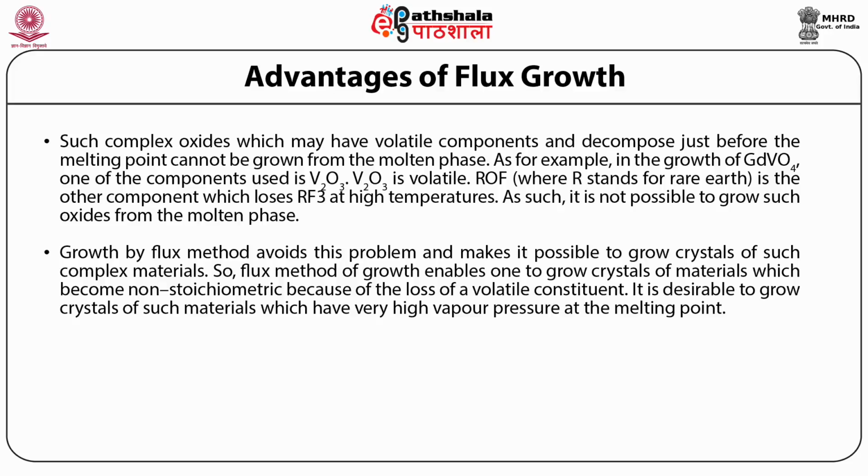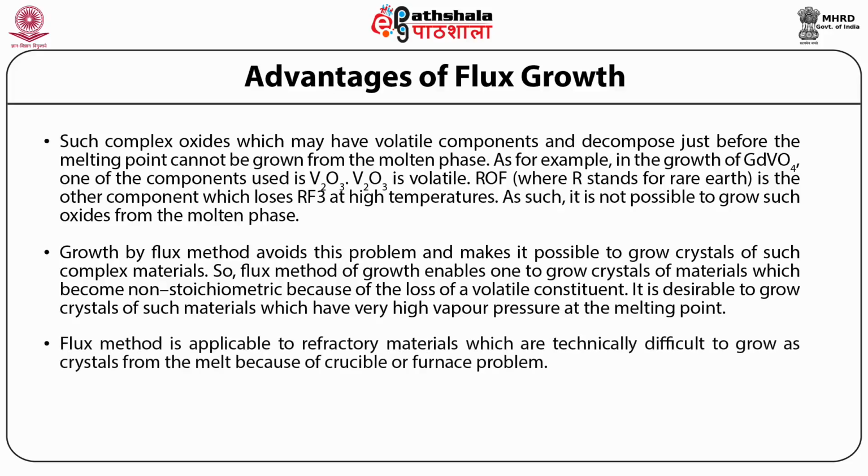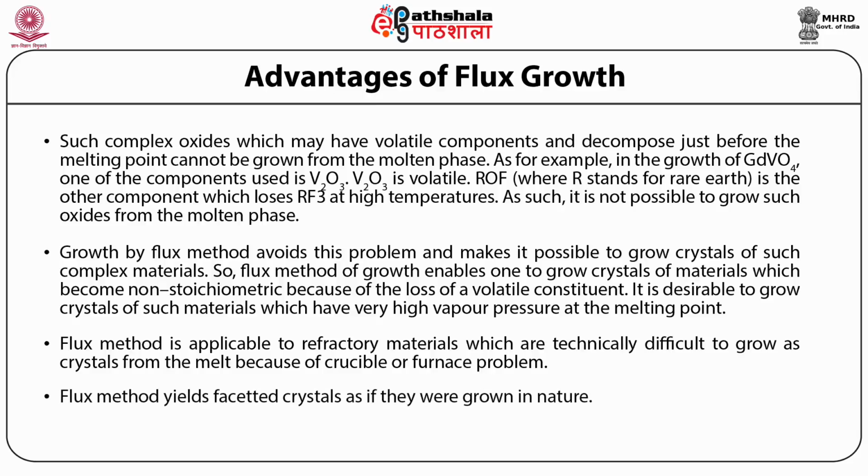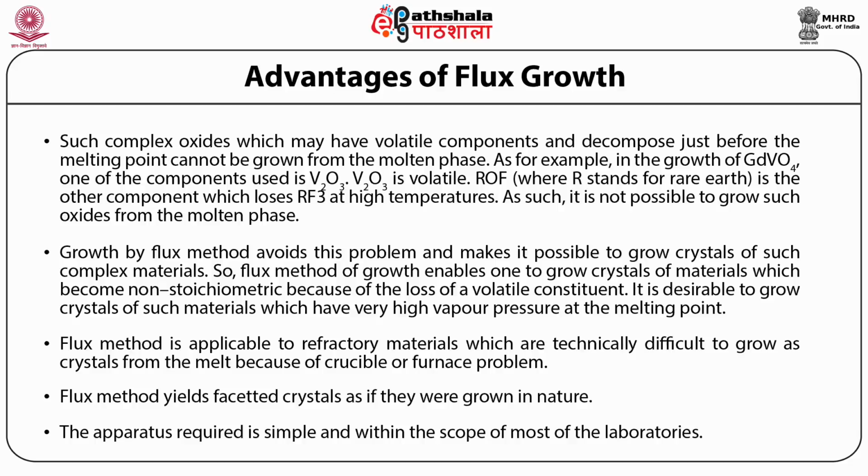It is desirable to grow crystals of such materials which have very high vapor pressure at the melting point. Flux method is applicable to refractory materials which are technically difficult to grow as crystals from the melt because of crucible or furnace problems. Flux method yields faceted crystals as if they were grown in nature. The apparatus required is simple and within the scope of most laboratories.